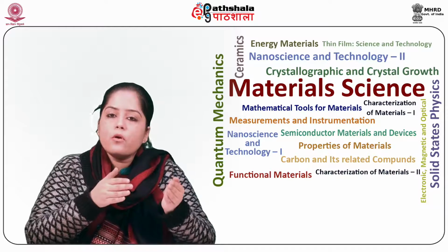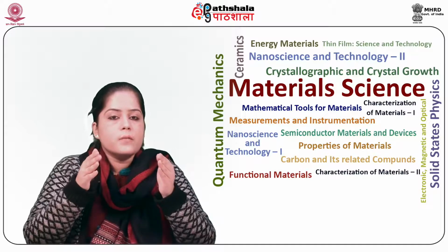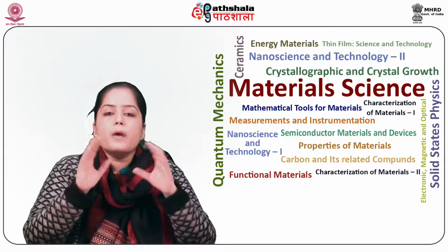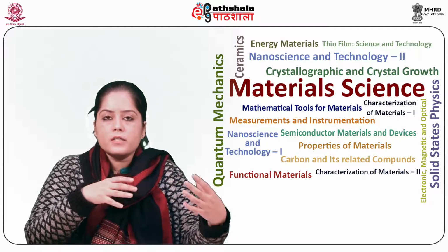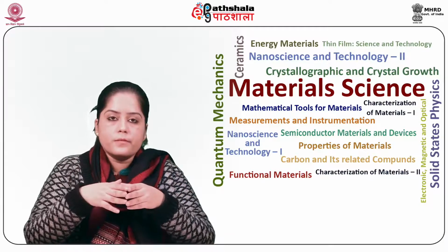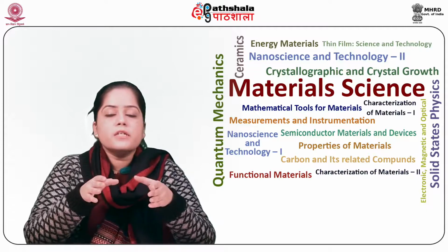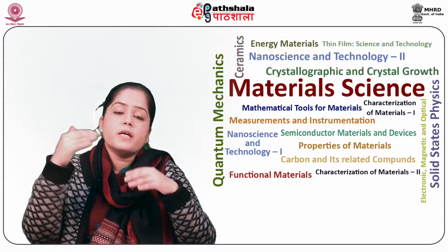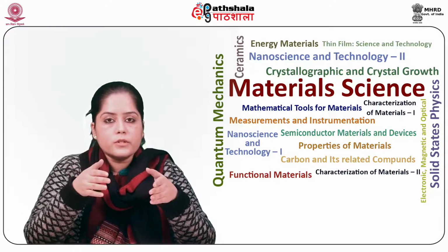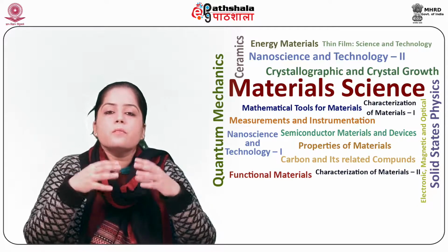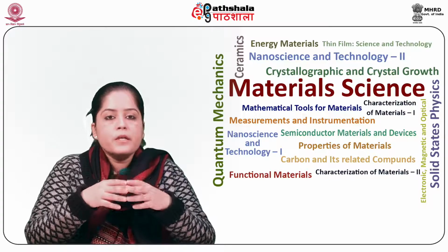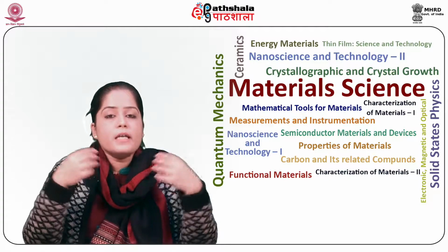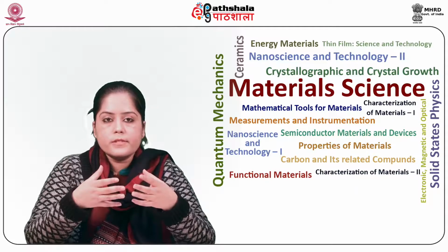Silicon in its pure or intrinsic state is a semiconductor having bulk electrical resistance somewhere between that of a conductor and an insulator. The conductivity of silicon can be raised by several orders of magnitude by introducing impurity atoms into the silicon crystal lattice. These dopants can supply either free electrons or holes.